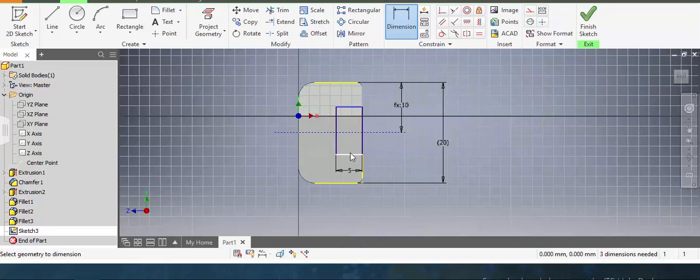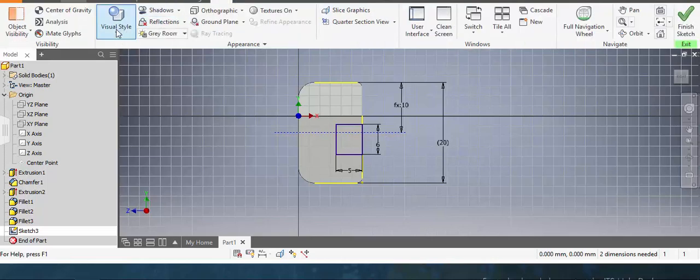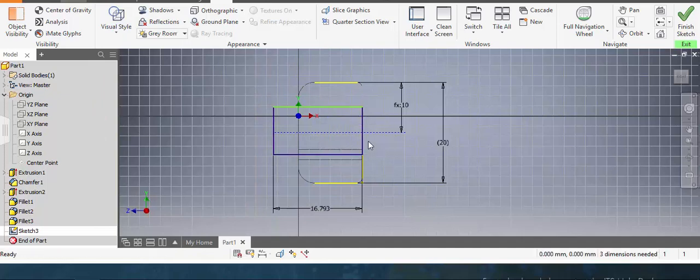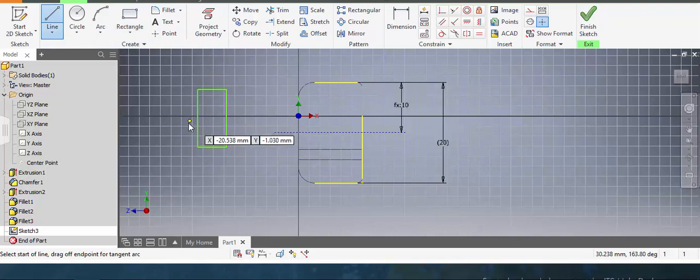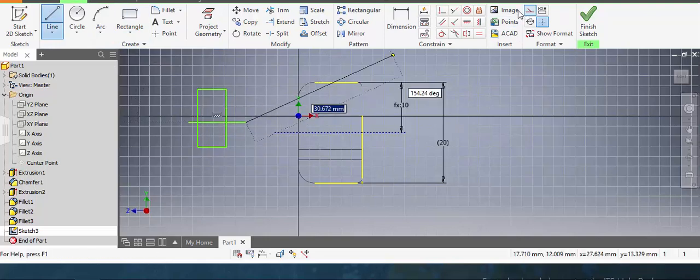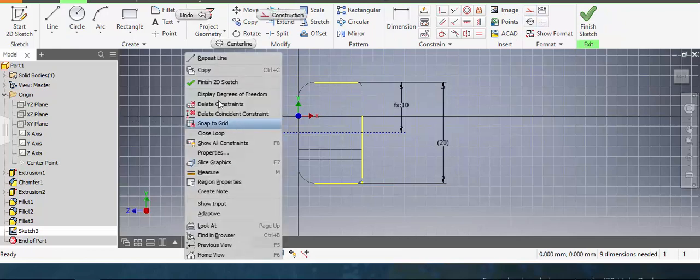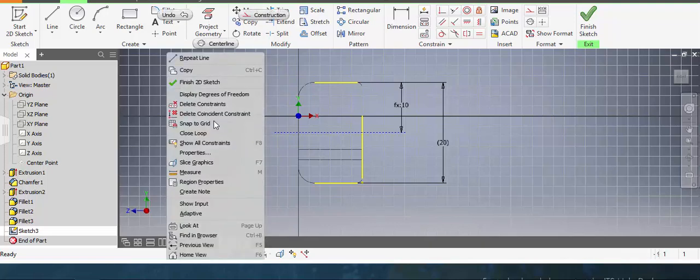And then if you want to have them disconnected completely, this is how you would do it. So you have aligned 2 planes in these 2 different holes. So this would be the way, and then we would just align it. And if something is not working, you see in the wireframe you can see what the things are, maybe it picks a midpoint. So I like to activate the wireframe constraint and then make it completely outside and make sure that I align, I convert the symmetry line to construction, and then I can align it there.